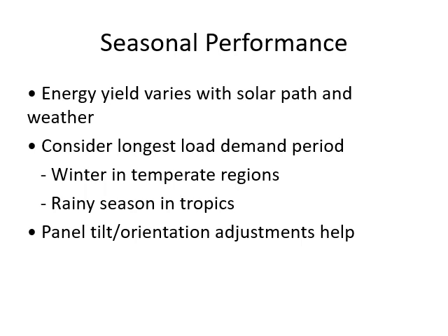In this case, the most we can do is panel tilt orientation adjustment, which will help take care of the seasonal performance. Previously you have seen that for winter we add 10 degrees and for summer we subtract 10 degrees for the tilt. So this kind of tracking can help.